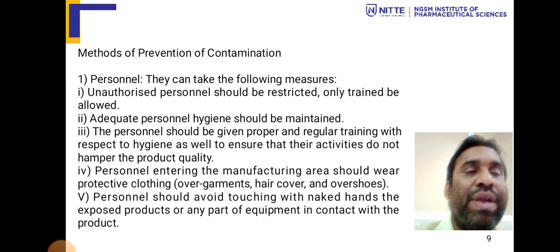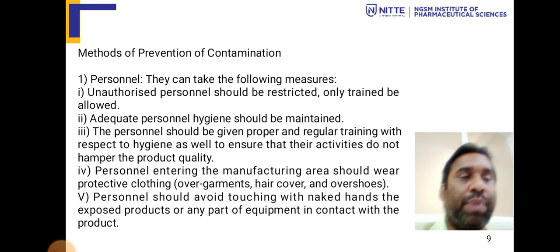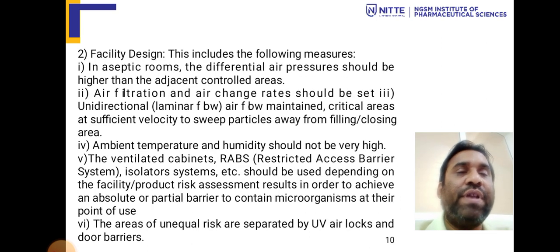Personnel entering the manufacturing area should wear protective clothing, overgarments, hair cover, and overshoes. Persons should avoid touching with naked hands, and exposing products to any part of the instrument or equipment in contact with the product. Facility design.